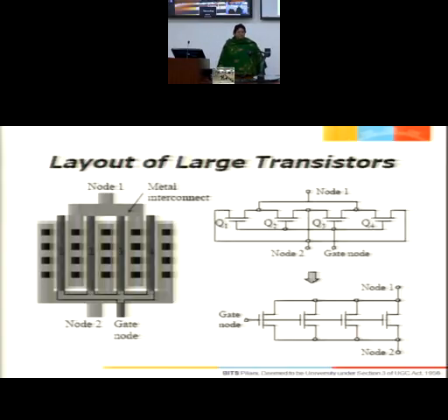So make a bigger component by using many small components. And all components that you are using should be standard, they should be the same, they should be matched, so that it is simply an extension of one current component multiplied by 4 or 3. That is possible only when you have matched components. So make a larger component. Here the component is going to be a transistor. Make a larger transistor by using many small transistors. Okay, so this is what leads to multi-gate fingered layout, because there are many gates now. I will have 4 gates.